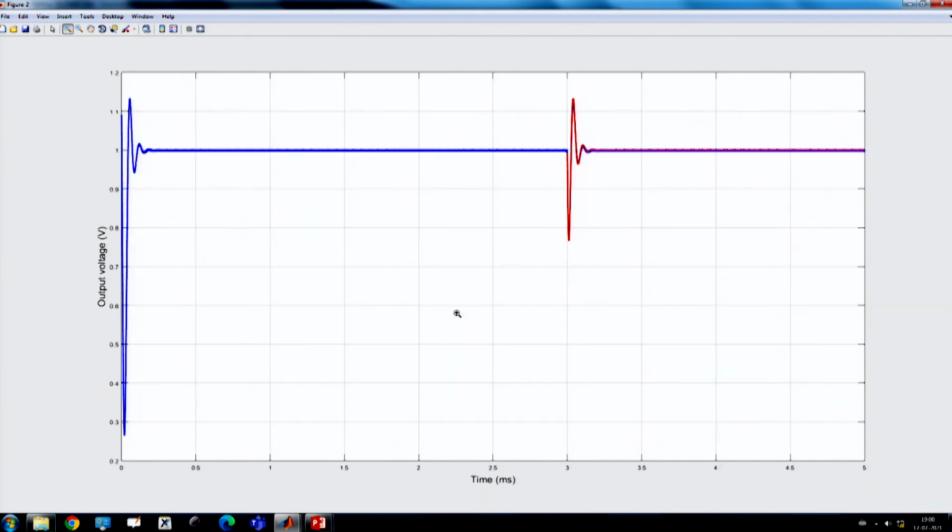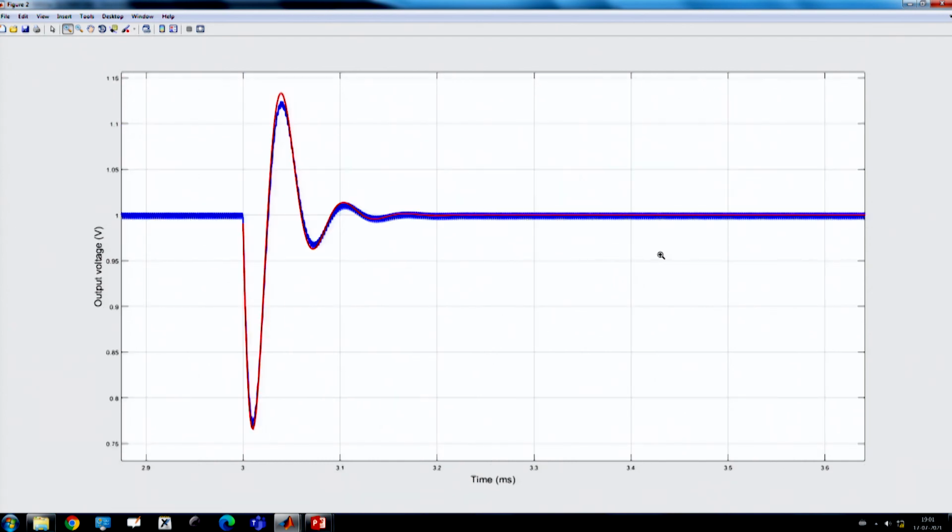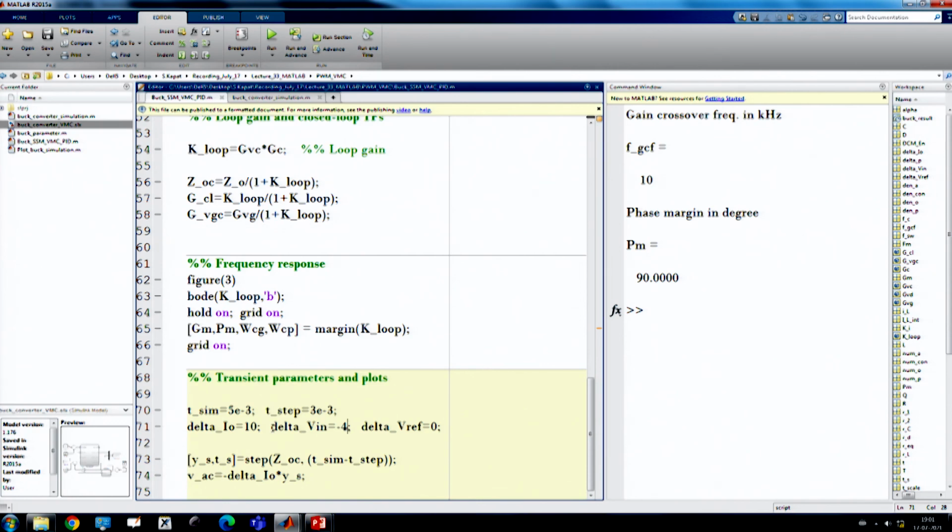So, that means as we push higher and higher gain, I can say the model matching using first order approximation is not the right solution. Once you go for type 3 compensator, you will get perfect matching even at 1/10 of the switching frequency. So, here because we want to achieve first order response, that is why it is not matching correctly. Okay? And here delta V in, our load transient is 0, it is multiplied and we need to use G. So, this one.